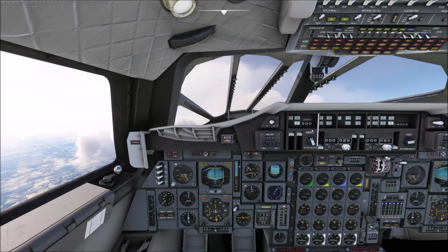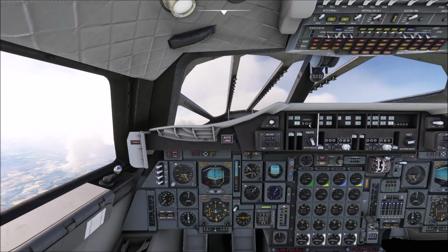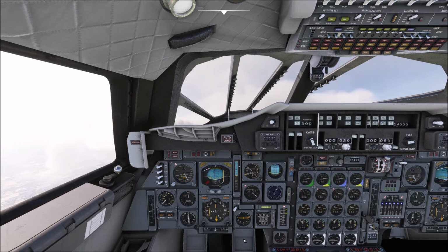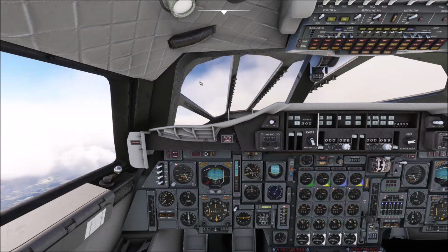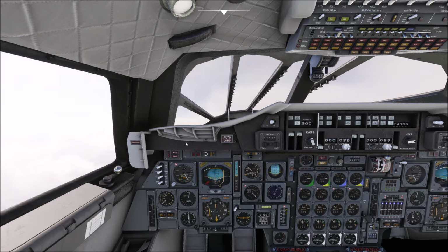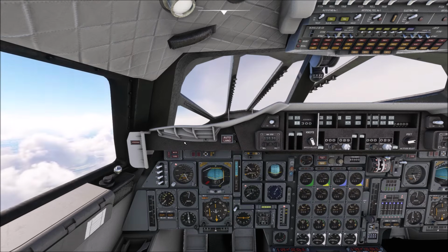As you can see, we're still on indicated airspeed, Mach 0.55. Concorde did not accelerate straight away to Mach 2. It would take often beyond an hour, sometimes 2 hours, to reach Mach 2. It all depended on air conditions, fuel weight, meteorological factors. Summertime, it's very warm over the Atlantic, even in the troposphere right up high, and Concorde just couldn't make Mach 2. It didn't always do it. It'd be like Mach 1.97, Mach 1.98.